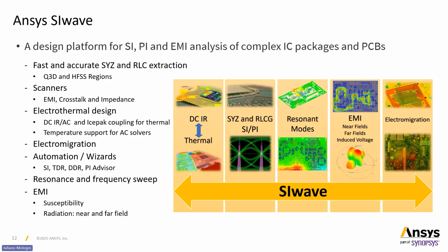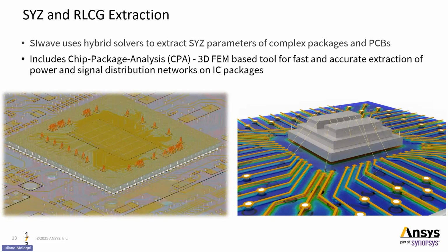You can compute near fields, which is what we use as a source for EMC Plus, and also radiated fields, far fields. You can simulate radiated immunity, induced voltage from a plane wave, and also electromigration. So one of the most used capabilities in SIwave is SYZ and RLCG extraction.